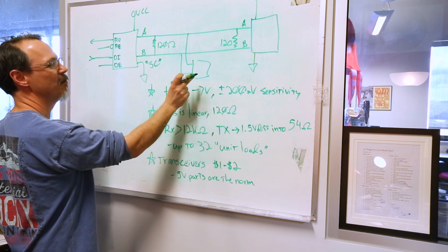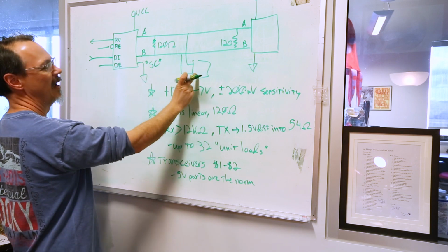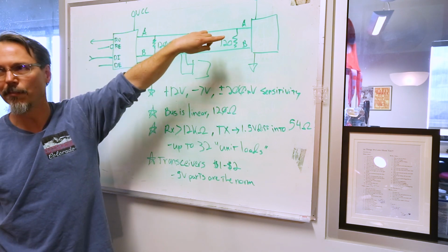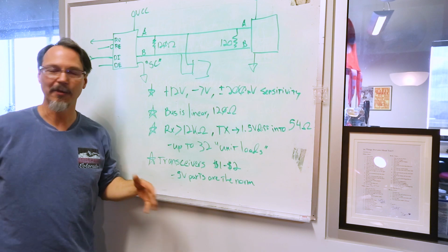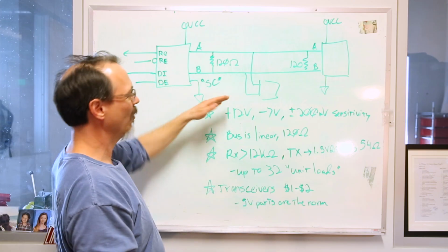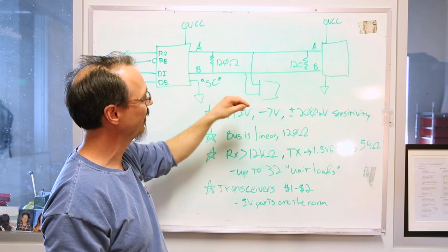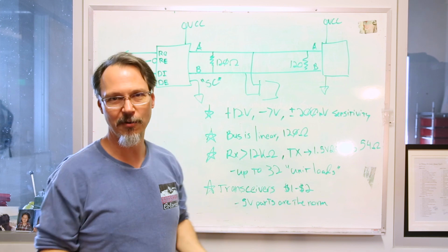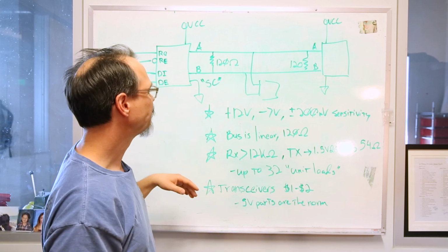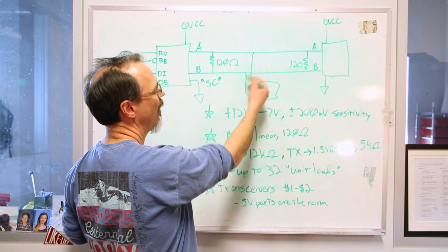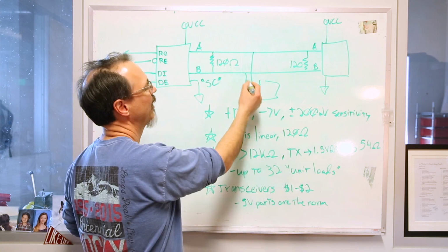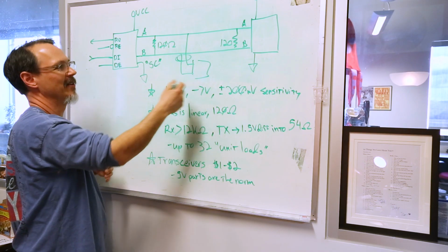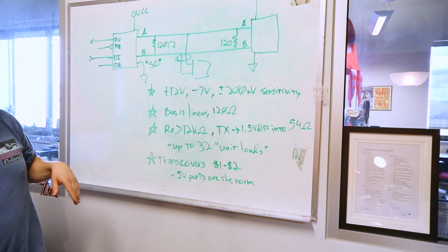So the rule about this is that you have to have any nodes in between at very close proximity, physically very close proximity to this linear bus. You can't have it shooting off a couple of feet. Why? Because this is a transmission line. The more you jack with that characteristic impedance, the less functional it's going to become. You'll start getting reflections, you'll get data corruption, yada, yada, yada. If you do need to offshoot to a farther location, they recommend putting a repeater circuit right in there so as to keep this one intact and that one will have its own. Kind of like that.